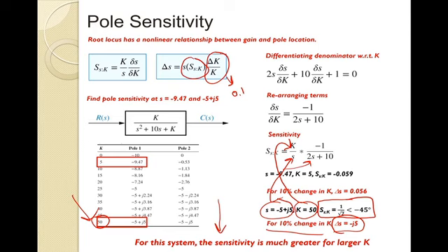Because what can happen over time is if your pole location changes, you might change damping, right? So the damping might get worse, you may have more overshoot, or some other factors as well. The settling time might increase. Something may change in your system, and so you may not get the response that you think you're going to have, maybe when it first came off the production line. But maybe 5 years down the road, there's a condition where the system wasn't as good of a design. Again, more overshoot, more settling time, something, and so the system would deteriorate.